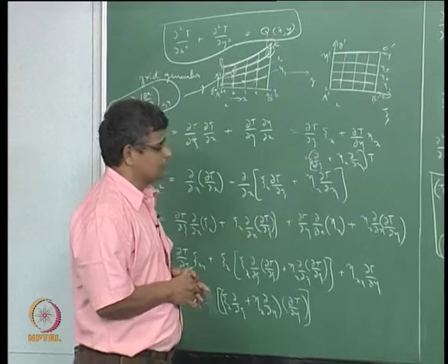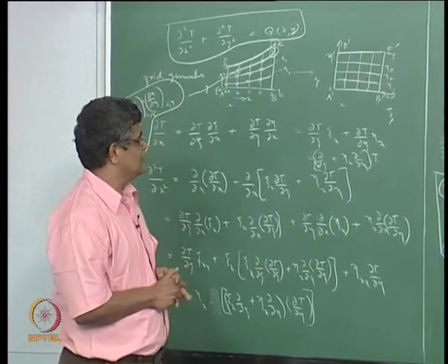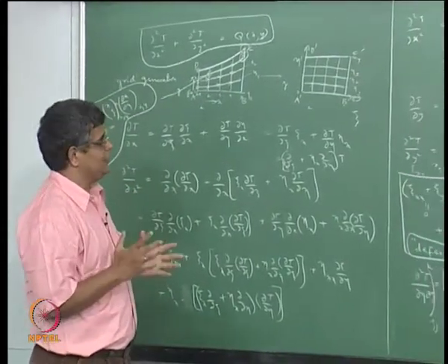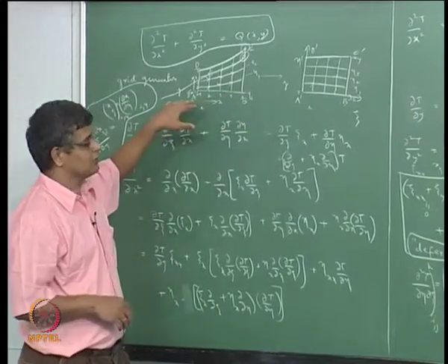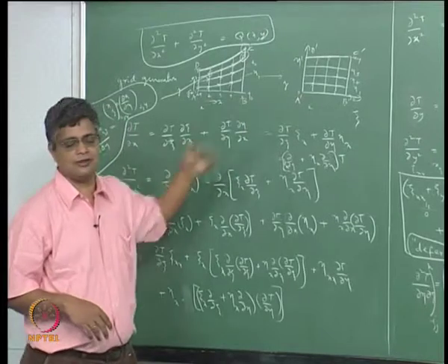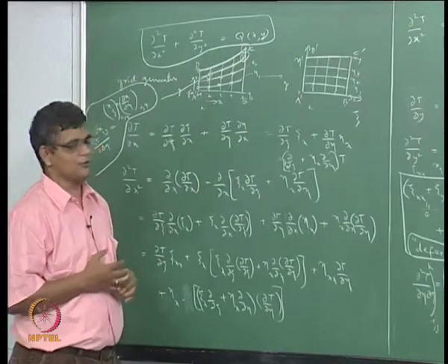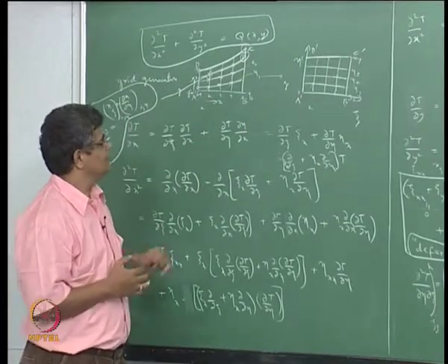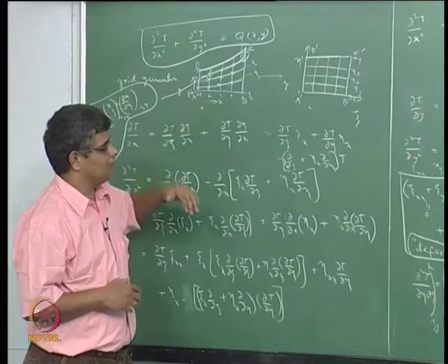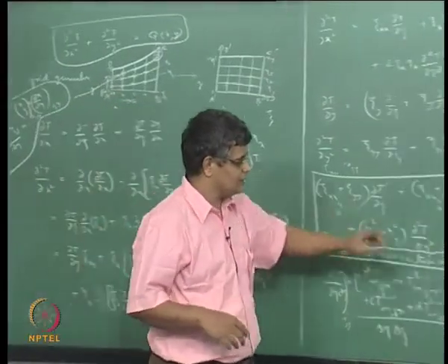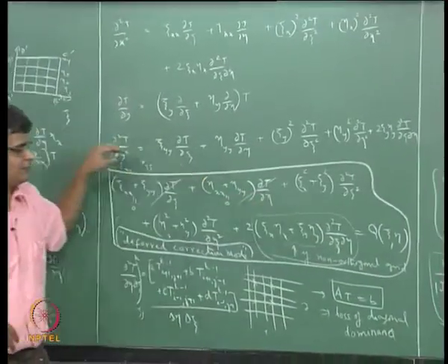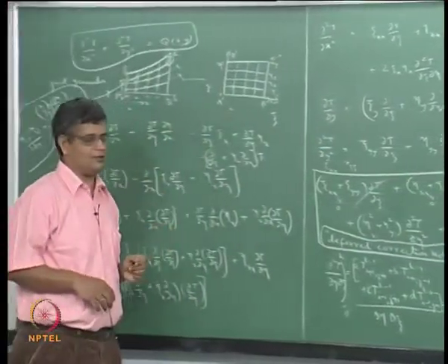If it is a completely two-dimensional problem, then it may be possible to generate a grid which is orthogonal. For example, if one uses the conformal mapping techniques, then one can come up with an orthogonal transformation, which will mean that the cross derivatives will not appear if the cross derivatives are not there in the original equation.